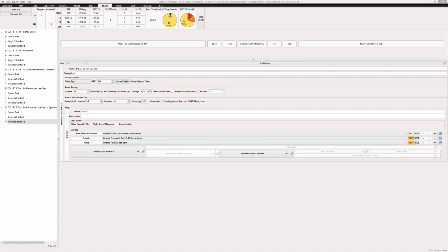There may be a requirement in there to perform a test and time the actual operation of the valve. That depends on the test that's required, or it may come from the overall actuator. How fast can we perform? And you may need to verify that with the expected response time of the final element. So yes, timing could be an important factor in the proof testing.